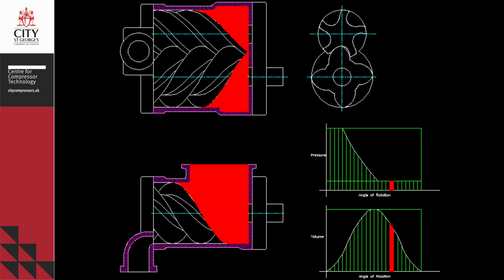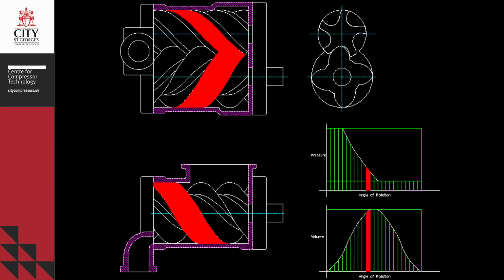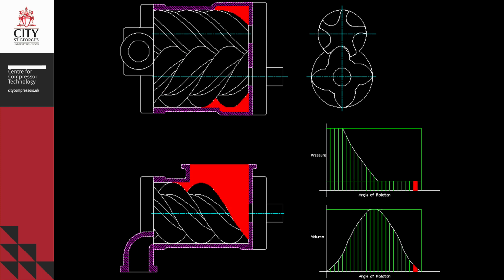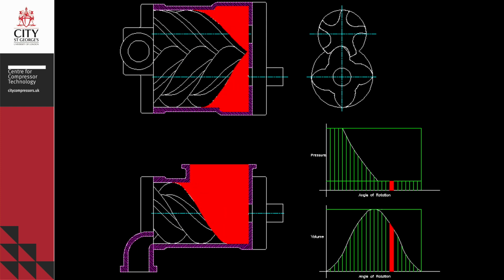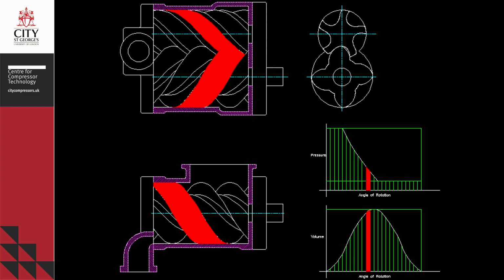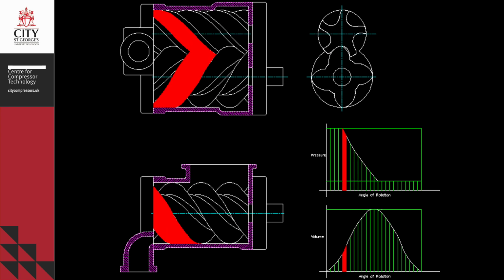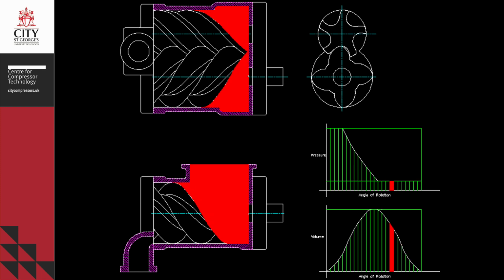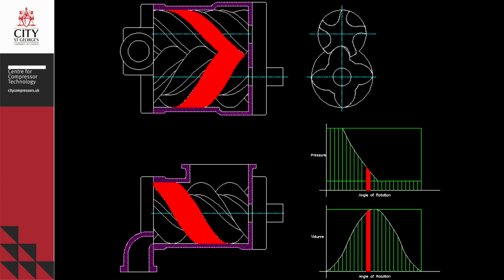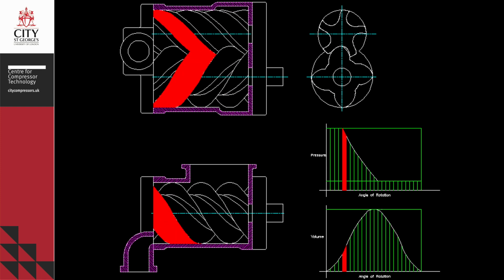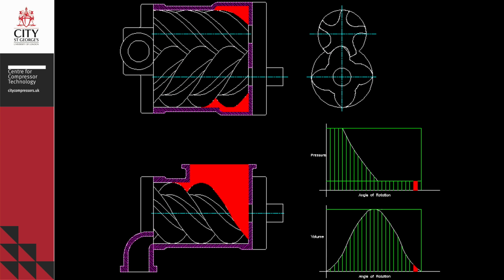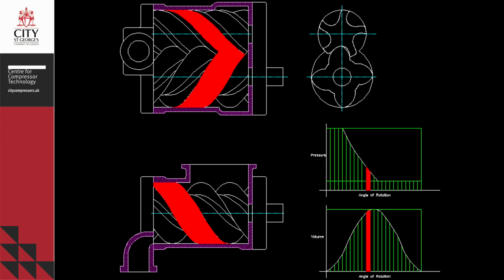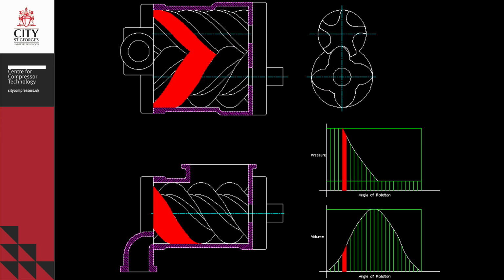In this slide, we can see an animation which shows the operation of a screw compressor in different projections. Since the rotors only rotate, because the machine has no reciprocating parts, it can rotate fast. Then, if we look into the animation carefully, we will see that the gas flow is more or less straight, allowing high shaft speeds and high flow of a relatively small machine compared with other compressors. There are no valves in that machine, which means that all troubles connected with the valves will be avoided.